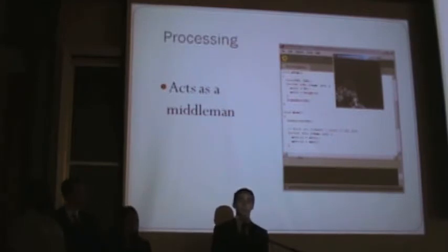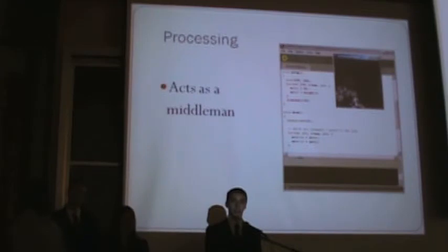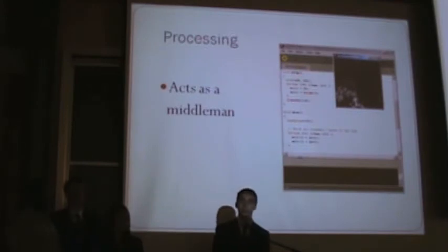Essentially, when the user inputs which appliances they're altering in BYOB, Processing reads this information as a string and looks for specific characters in that string to determine which appliance is being altered and how it's being altered. From there, Processing sends this information down a USB cable to an Arduino microcontroller.